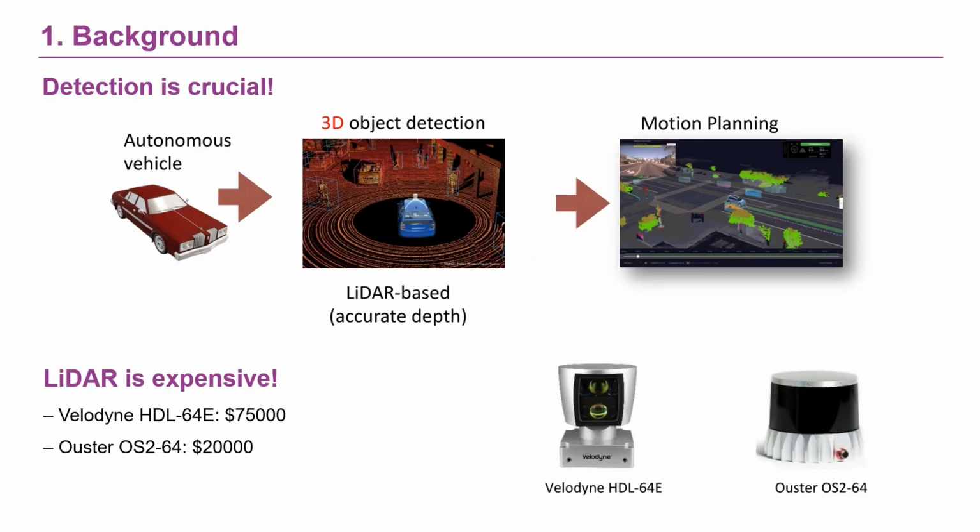3D object detection, responsible for providing precise 3D bounding boxes of surrounding objects, is an essential environmental perception task in autonomous driving. Recently, relying on the accurate depth measurements of LiDAR, LiDAR-based detectors have achieved superior performance. Several intrinsic deficiencies of the LiDAR system, such as high cost and sensitivity to adverse weather conditions, inevitably impose limitations on the applications of these methods. In contrast, camera sensors are more economical, robust in rain and snow, and feasible to satisfy strict vehicle regulations.